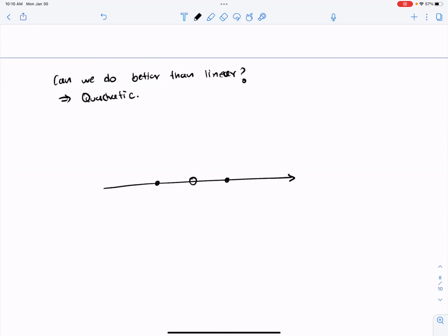So you cannot define a parabola uniquely with just 2 points. You need 3 points. So a quadratic element will need 3 nodes, just because you need 3 values to define a parabola. So we're going to call this x1e, we're going to call this x2e, and we're going to call this x3e. So 3 nodes needed to define a parabola.